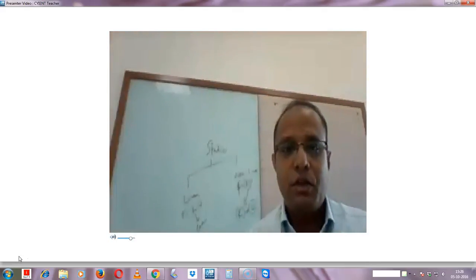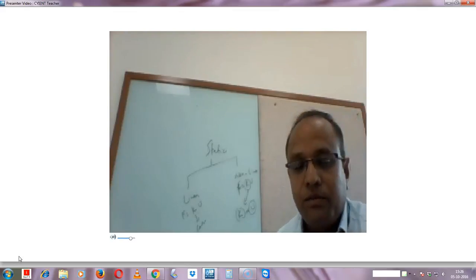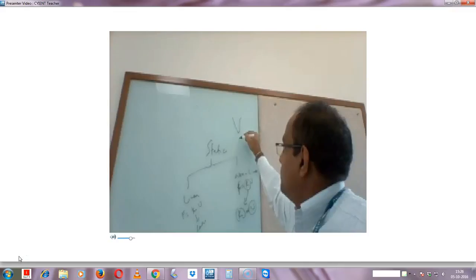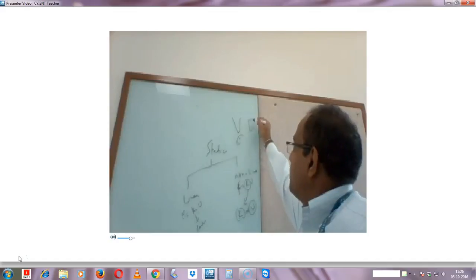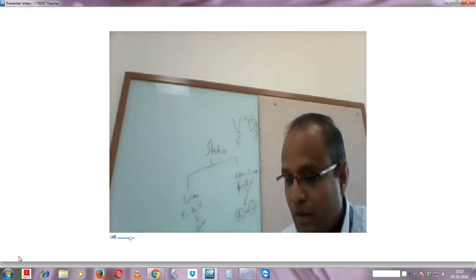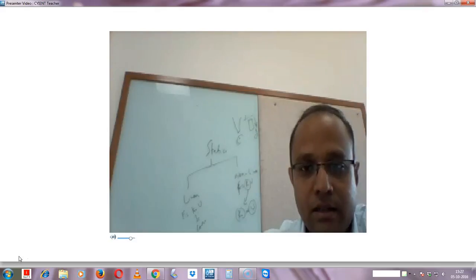So what can we do with the steady loads? What types of loads can we apply? We can apply gravity loads, rotational velocities, that is inertia loads, when a rotor is subjected to uniform angular velocity, or when a bar is subjected to vertical gravity load. Or you can apply temperature, thermal gradients, pressures, and point loads. All those types of loads can be applied in static analysis.